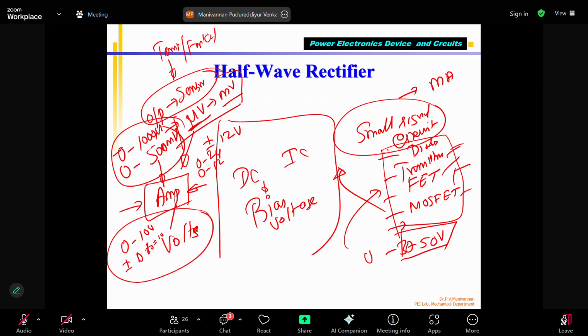For example, I have an op-amp, and I give it plus 12 volts and 0 volts. This is a thermocouple, TC, which generates 0 to 50 millivolts when the input temperature varies from 0 to 1000 degrees centigrade. What will be the maximum output voltage, V out? Anybody? And I say that the differential gain AD is 1000. What is the output?